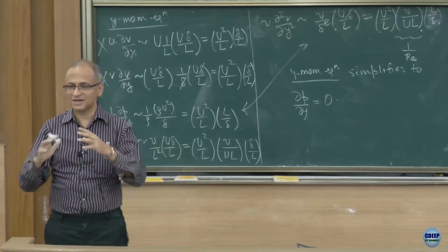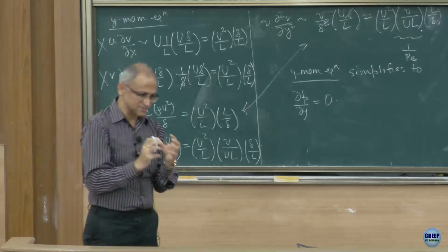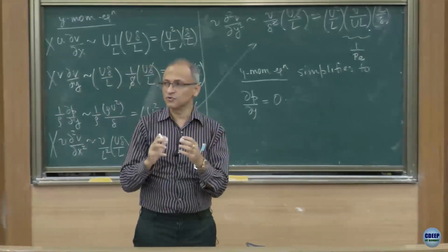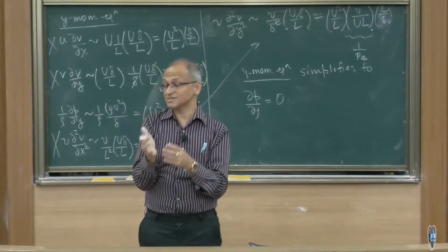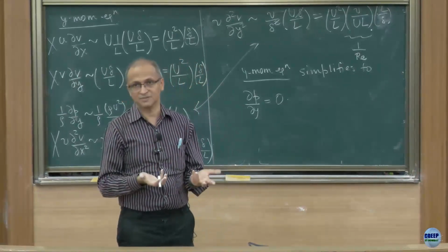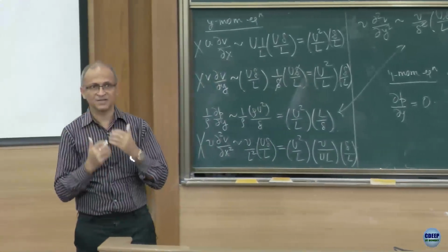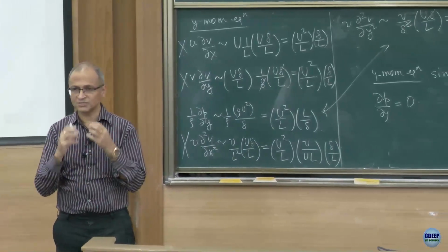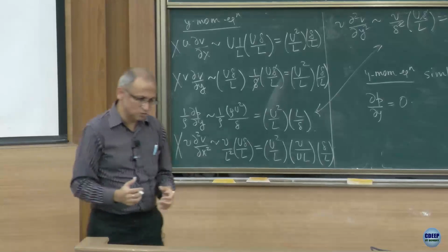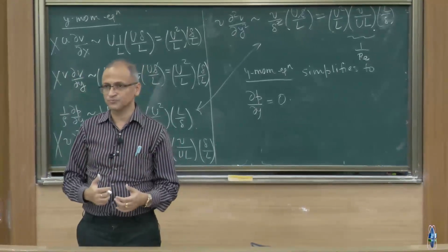Now what we are saying is that there will always be a region where viscous effects will be important. Otherwise we will have to start applying the slip condition, which we know is not applicable, because the flow does not slip on the surface. That means that something in our analysis was not done correctly earlier, and that is because we decided to ignore the viscous terms altogether, whereas now we are saying that that is not exactly true.